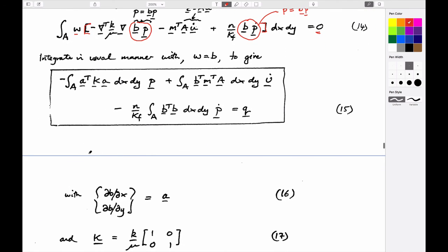And so we could write this, in terms of our own terminology, I think we called this previously Kf multiplied by nodal values of fluid pressures. So this is this. This is our conductance matrix, finite element conductance matrix.